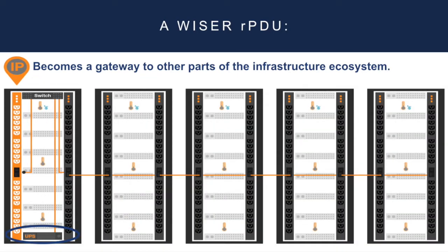Finally, using the same graphic, we're highlighting another related component, a rack mount UPS here at the bottom in this blue circle. Rack UPSs are very pervasive in smaller IT environments, edge deployments as they're often called, and they are a vital part of that power chain, working in tandem to back up the power provided by the rack PDU. Since their work is interrelated, a wiser PDU, through its embedded systems and its UI, should allow some level of integration with the UPS so that I can see the values of a UPS in the same single pane of glass, if you will, as the values captured by the rack PDU, since they're related in that power one-line.